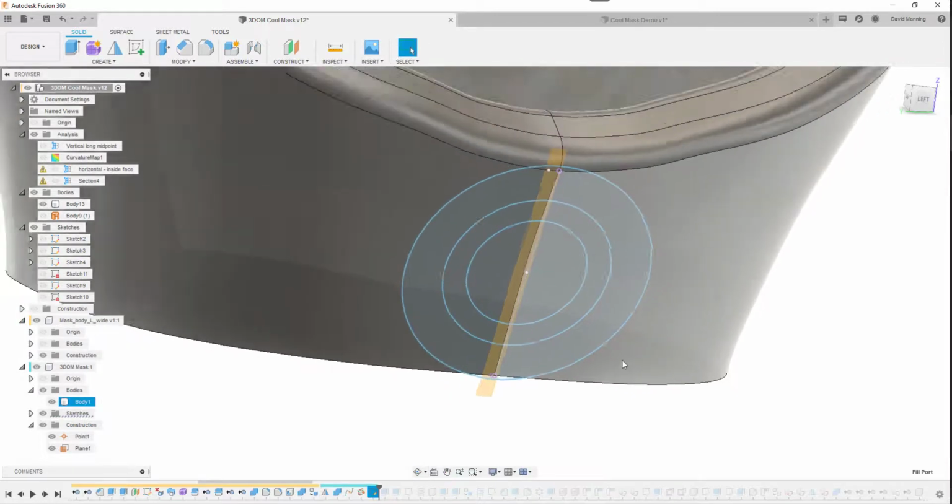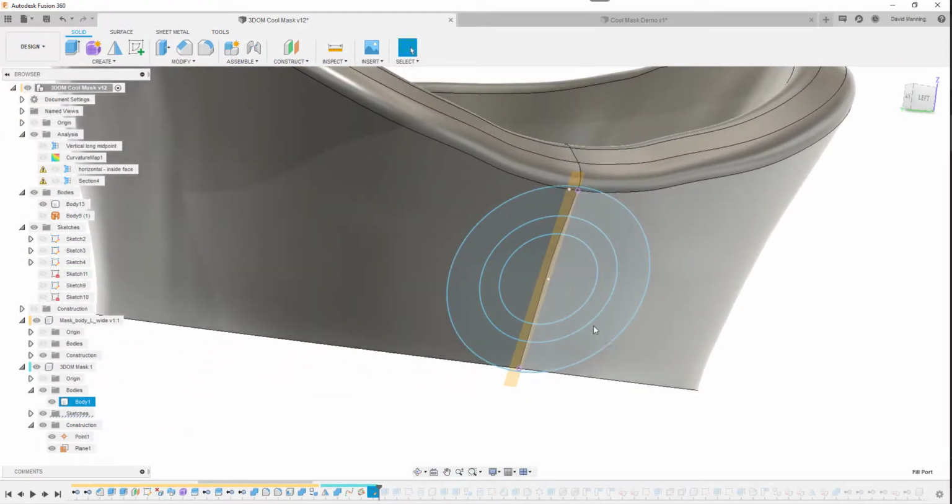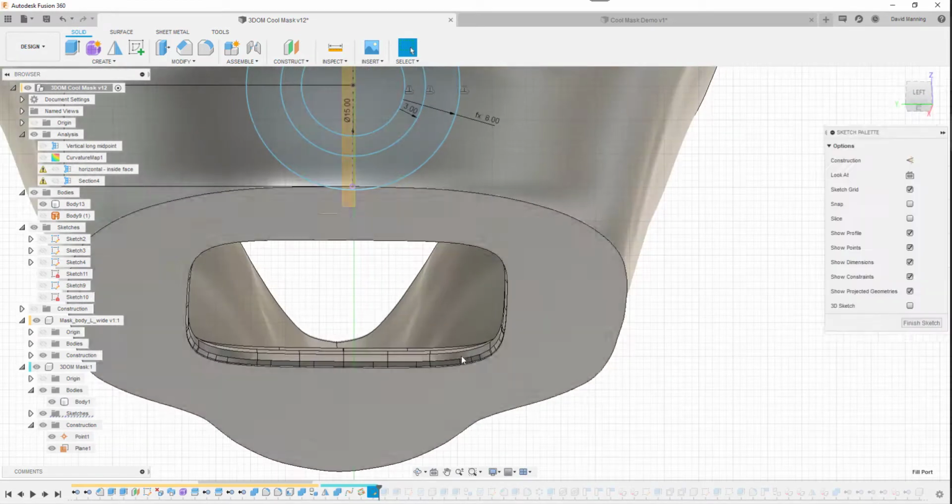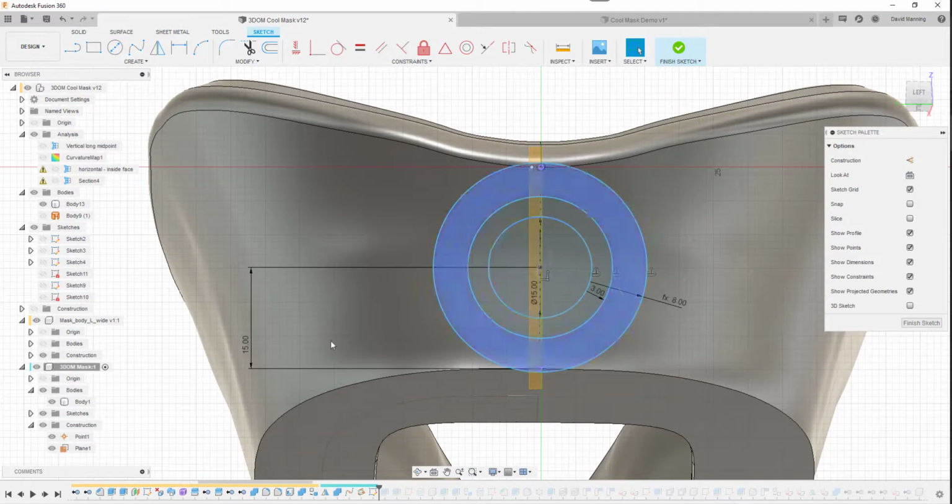Now there's a lot of fiddling around trying to figure out exactly the right size, but what we're looking at here is basically one ring. Let's edit that for the sizes. I've defined how far up I want that to be from this node, which is projected, and the size of the hole that I want. I want it to be reasonably big to be able to get the stuff in there without too much trouble, but not too big, because the cap that goes on it needs to be bigger, and I don't want it to be too much bigger. So I've decided I want 15 mil. I want a 3 mil wall thickness for it, so that gives me a cylinder I can project, and this outside one here, 8 millimeters, I can use for the cap.